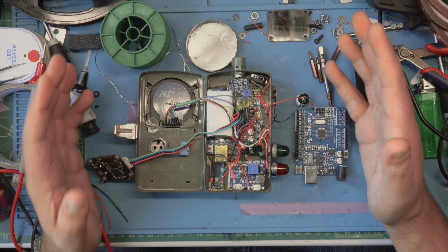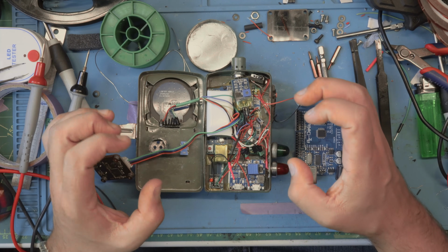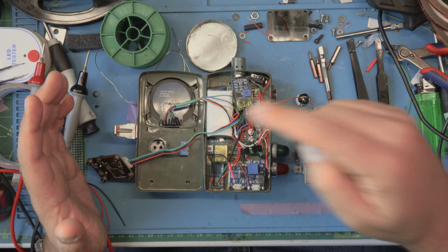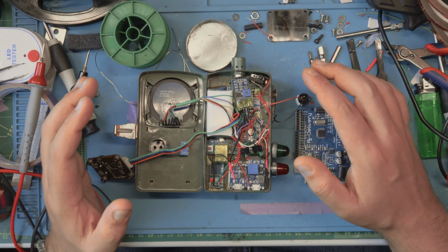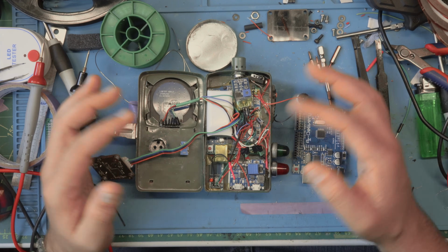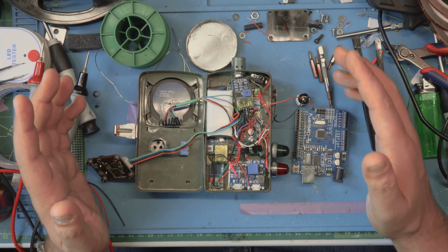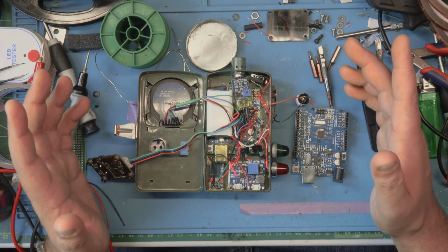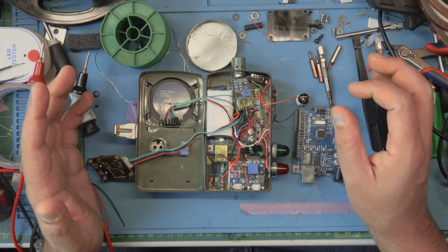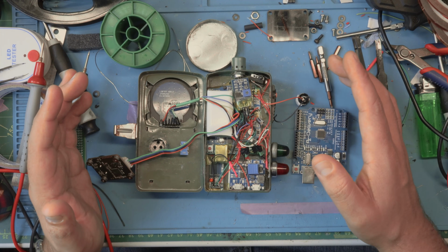But here is what actually happens. Everything draws current at one single point when you turn this thing on. So there is a drop of voltage, which can be enough to keep the Arduino board from booting. When the Arduino board just idles and does not boot, nothing will happen. All the parts are on and everything is working, but there is nothing going on because the board is not booted. Now it turns out there is a very simple fix: delay the boot sequence for just a tiny amount of time in order to power everything up and then boot the Arduino. And well, it's easy.